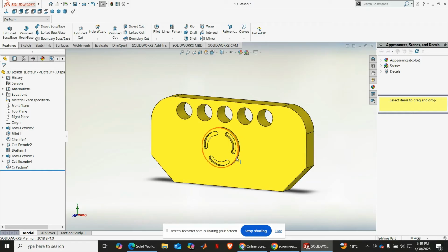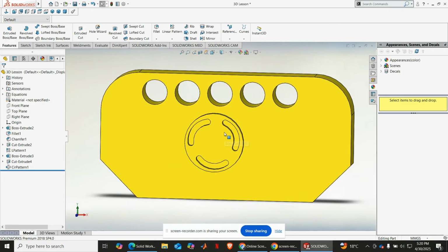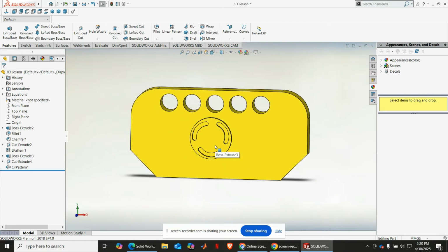So let's say now you have to know every object that is mirrored is normally inverted, like inakuwa ni true but vice versa. Like if you mirror this feature it will look like it is like this. So if you put a mirror here, this feature will look like that, like it's inverse, right? In reverse. That's how it's a reflection. Okay, but if you mirror a cycle, you won't see a difference because it's just a cycle. But if it was an open sketch, you will see it inverted.